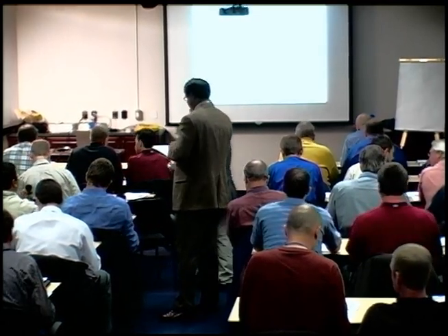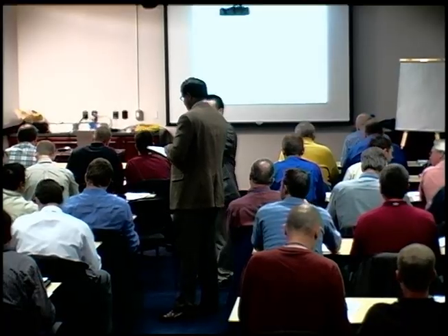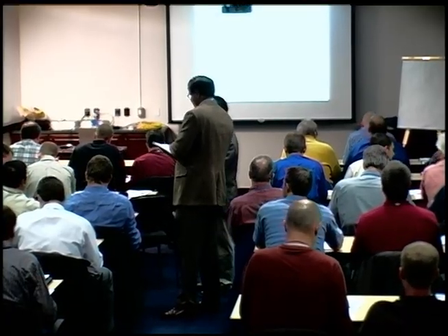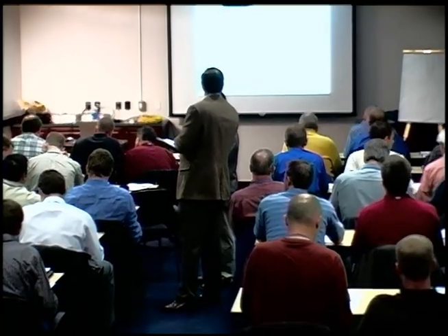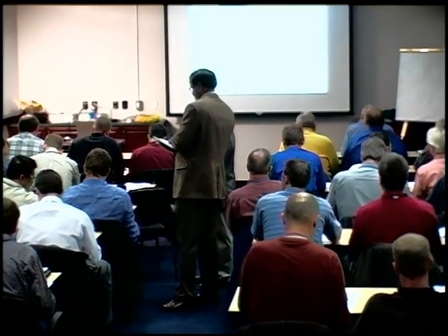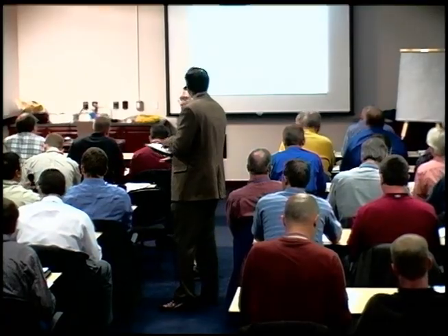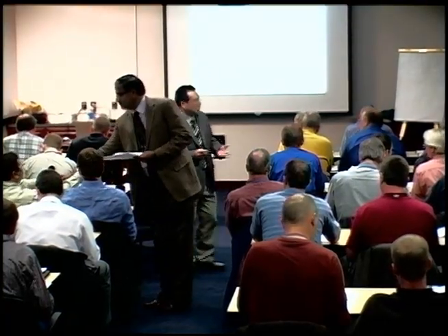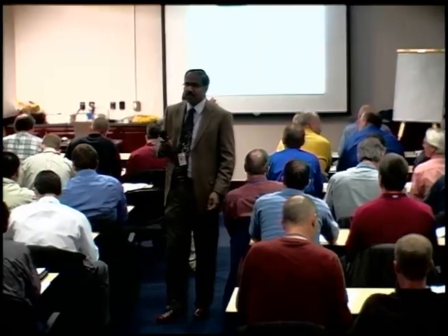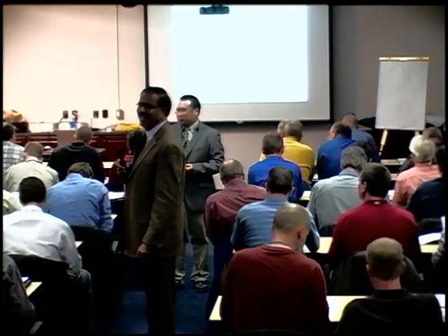It could be an error. Yeah, it should be around 3.2 based on the design chart. For medium sand under wood pile, I must have selected under the steel pile. Yeah. Good point. So that number, 2.8, should be around 3.2 if it's based on the design chart. All right? Interpolated that.